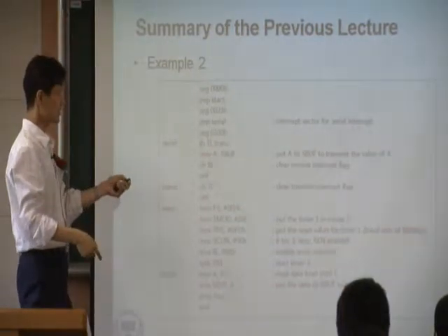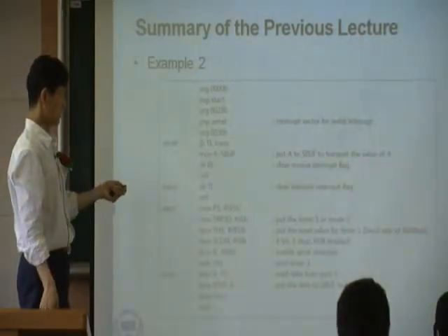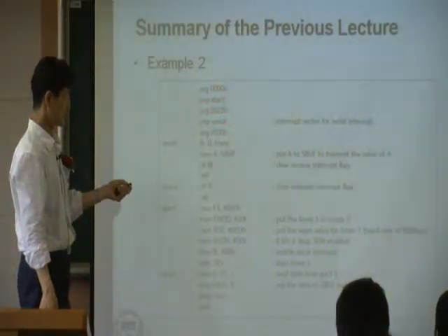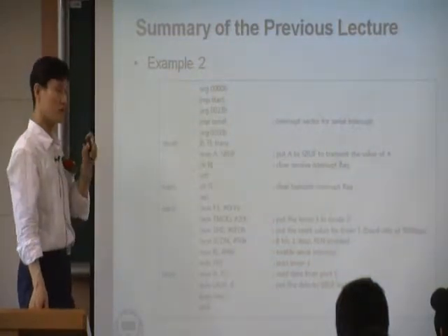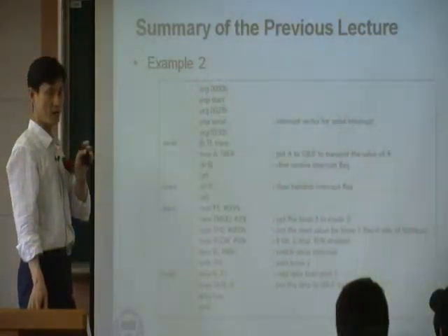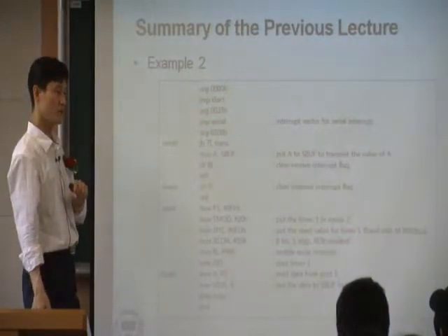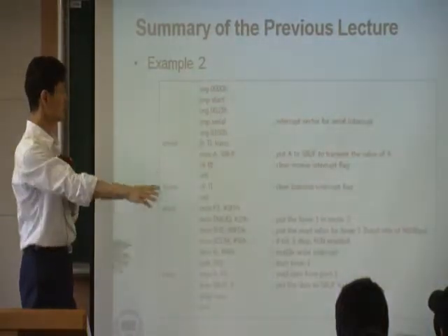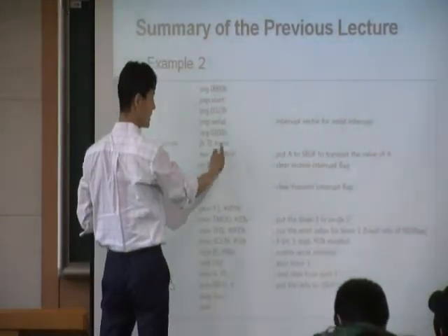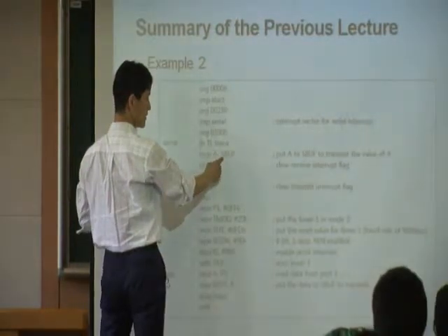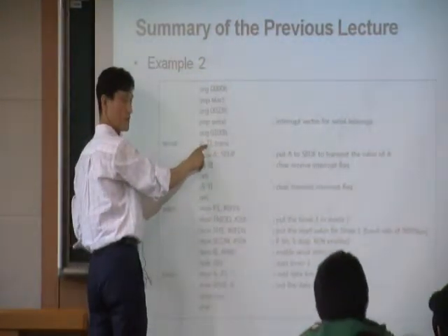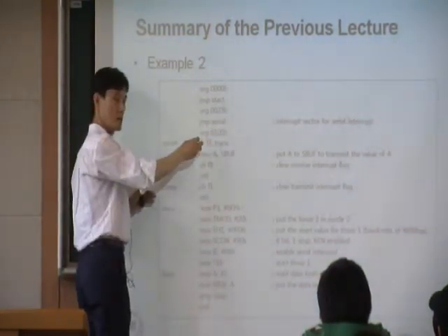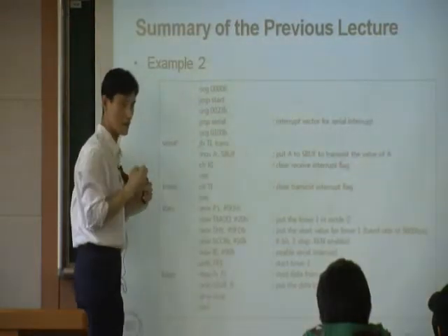First of all, in the interrupt service routine, in serial communication, we have TI, the transmit interrupt, and RI, the receive interrupt. For the transmit interrupt, you don't have to do anything. But for the receive interrupt, you have to copy the value. If it was a transmit interrupt, you can still come here, because when TI equals 1, you still get an interrupt from the hardware.